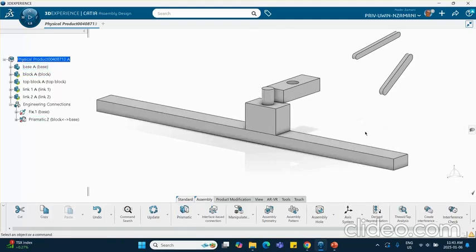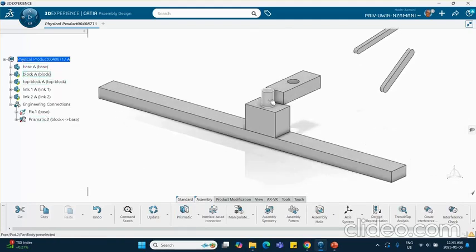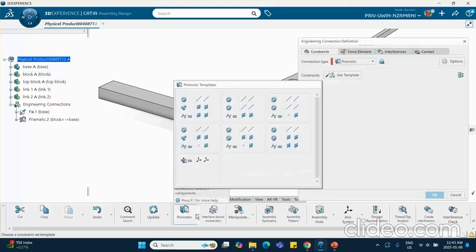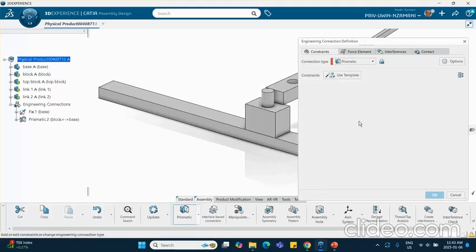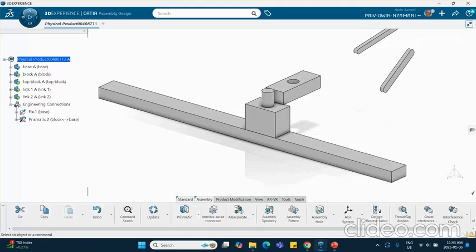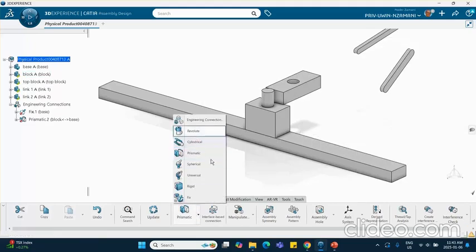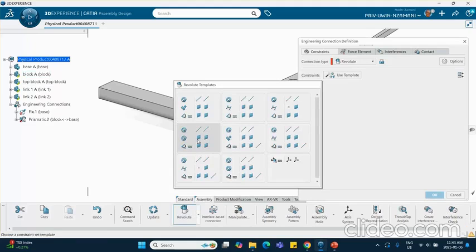You can see that. Then I'm going to do a revolute by putting this block on top of that. Let me see. No, this is a prismatic. Sorry, cancel that. Let me use a revolute right there. And my favorite one is this fourth template here: edge, in principle, axis and axis, plane and plane, coincident, and then angle between 2 planes. So I'll use this one.